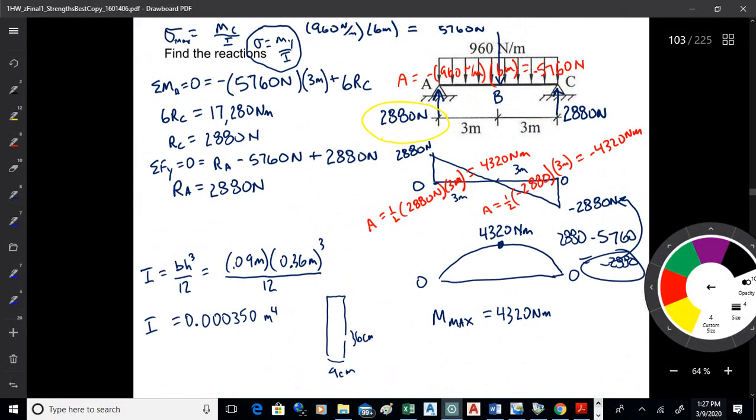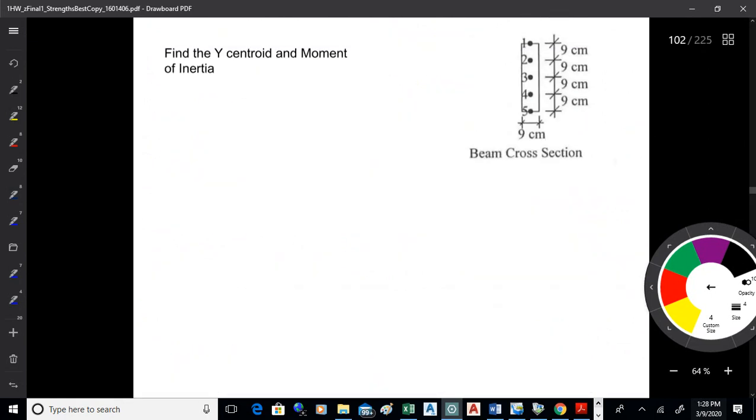Now 351, this one's very similar, except it's not quite as complicated. It's just a simple beam that bows down. It's also just a rectangular beam, so that makes the C's equal everywhere. But on this one, here's your neutral axis. What we're doing on this one is using sigma equals My over I, because we're asking what's the stress at these different points. So you just got to find the different y values.